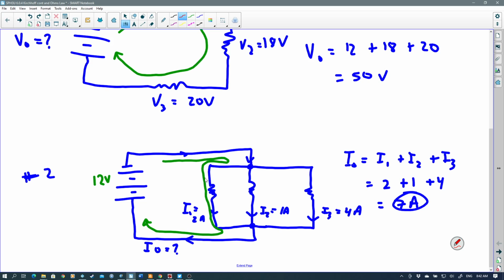In the next circuit, which would be this one, same thing happens. You gain 12 volts, you lose 12 volts. And the last circuit, which would be this one, once again, you gain 12 volts, you lose 12 volts. So these 3 resistors, if you remember, are called resistors in parallel. They all have the exact same voltage as the battery. So they're stealing the 12 volts from the battery as the electrons go through.